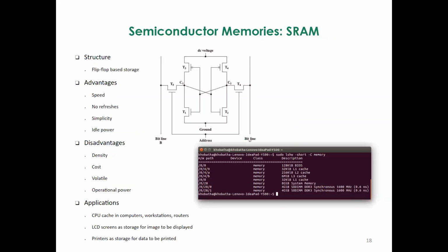Okay, so SRAM, already we have discussed it, and also that it's built from flip-flops. Of course, you can see this one is making use of 4 or 6 transistors to make one SRAM cell. And the nice thing about it is that it's very fast. There's no need for refreshes, and it's also relatively easy to design.